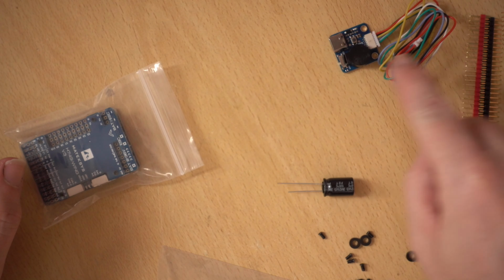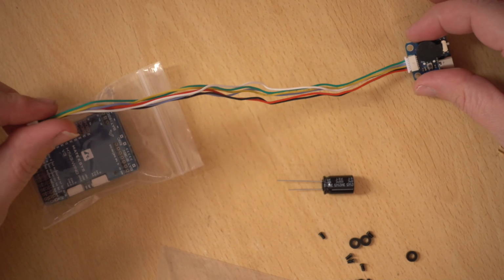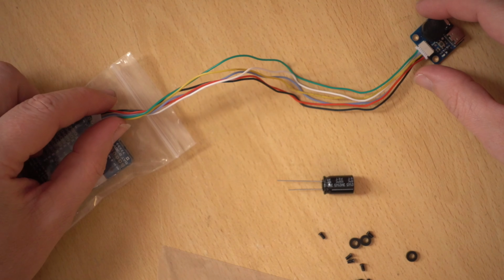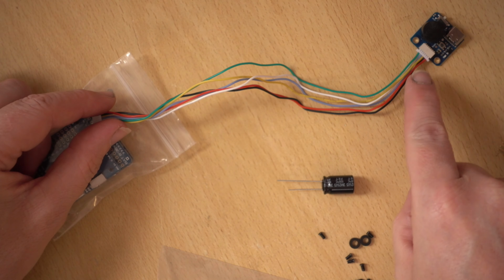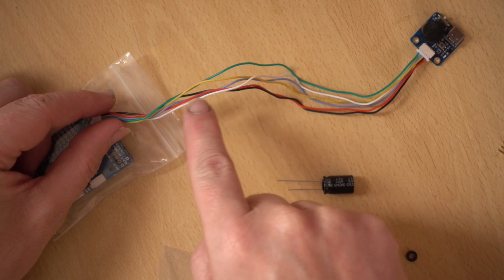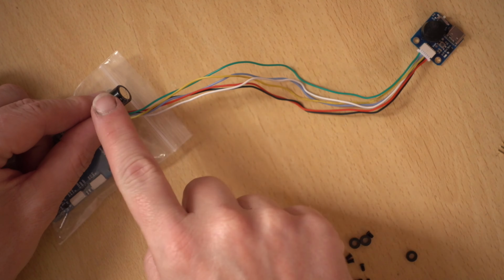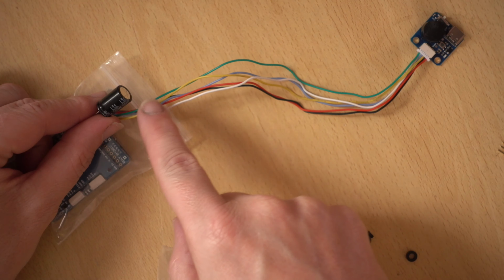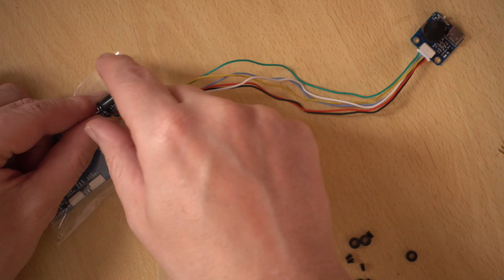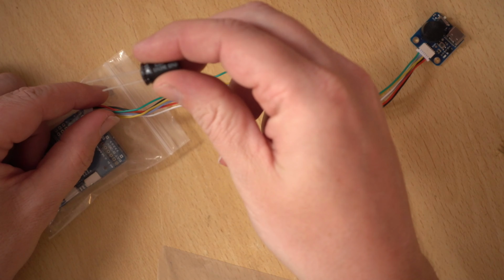You've obviously got cables, so we've got our main power and ground going to our ESC. If this is generating noise, then that noise is going to get worse and worse as it travels along the cable. So putting this capacitor here, the amount of noise it can get rid of is the same at either end. But if the noise has amplified through the cable, this has got more noise that it has to try and get rid of, and it might not be able to do that.